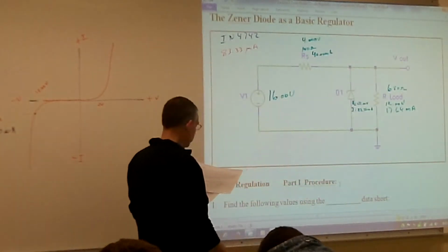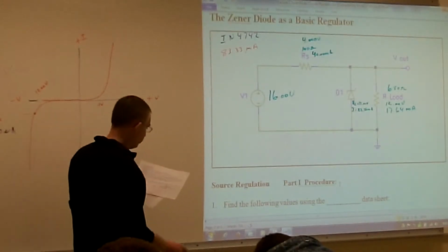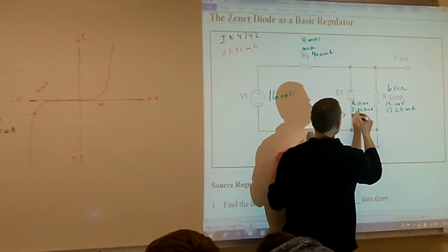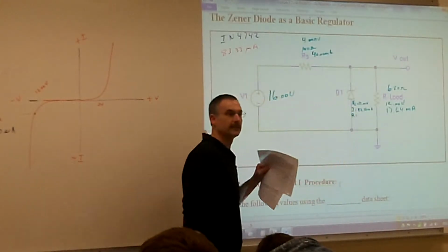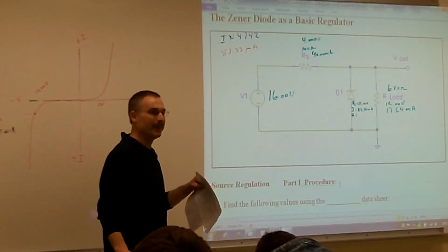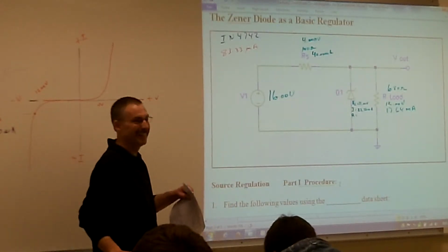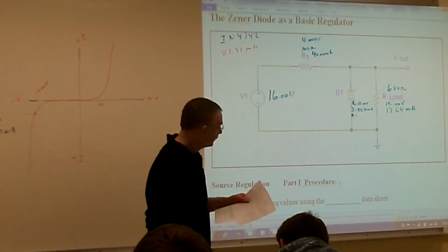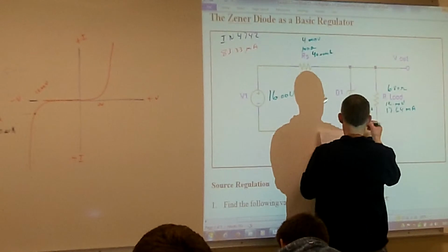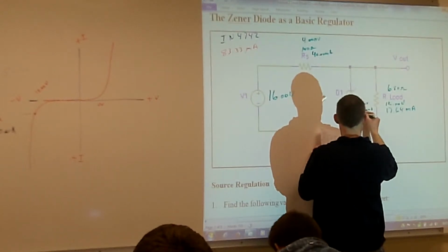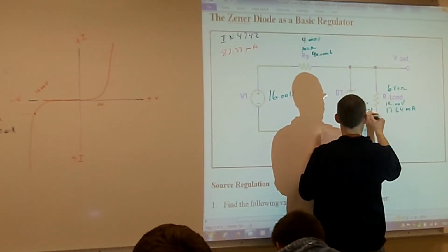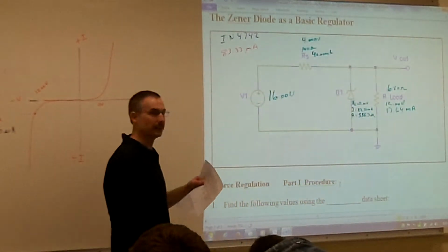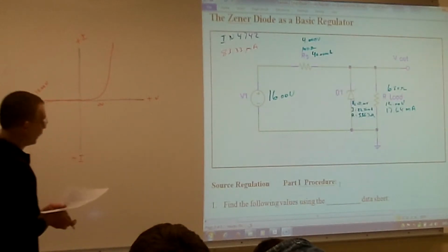Okay, what's my resistance of my Zener now? A lot less? No, a lot more. In between less and more? Either or. 536.7 ohms. Yeah, so a lot more, not a lot less. Right. Got less current going through there, so we got more resistance.